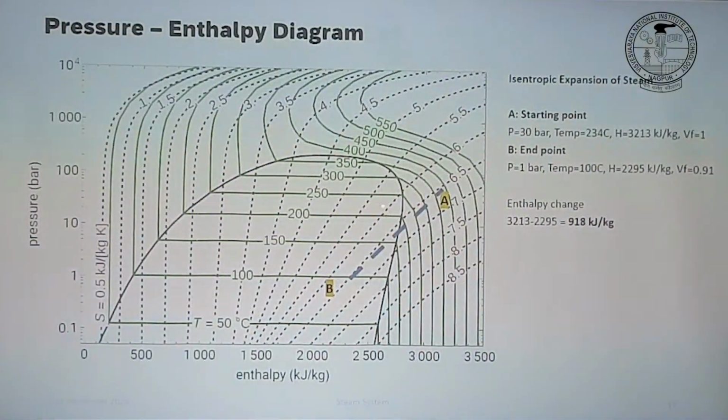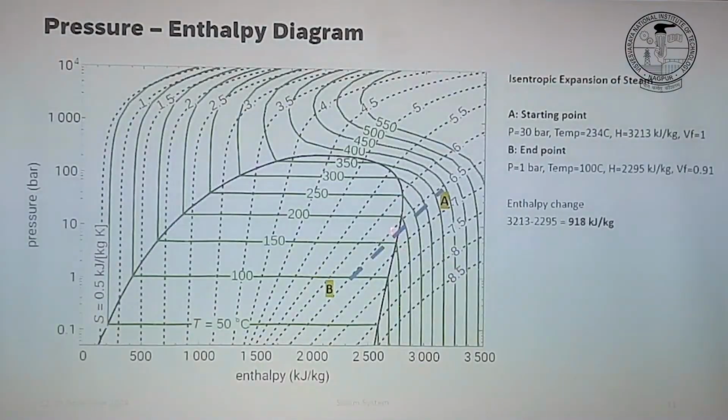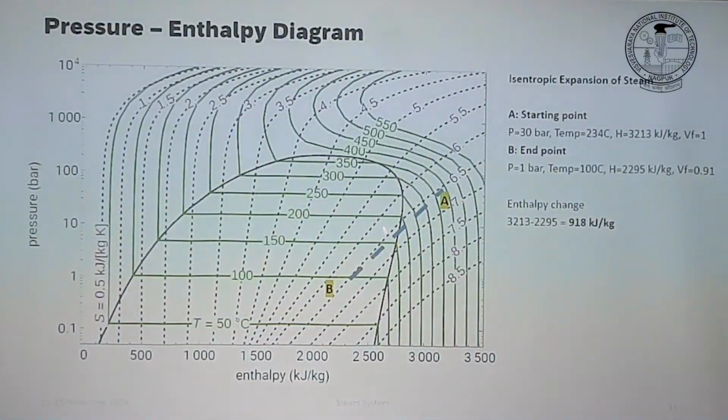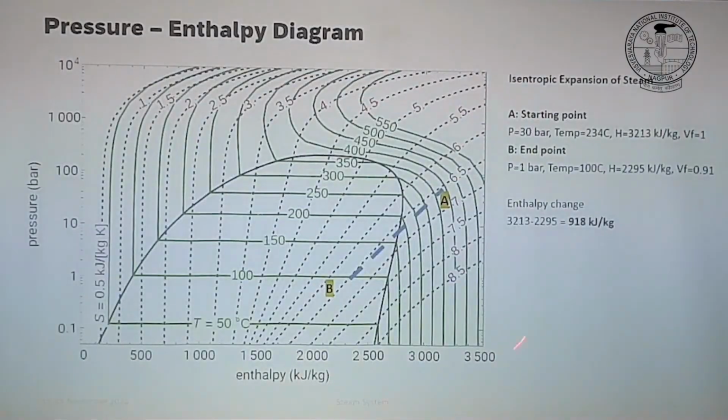What else can we do? We can superheat the steam, right? So we are not at the saturation curve, but now we move from the saturation curve to the superheated region, thereby increasing the enthalpy of point A. Right? And with this, you now have much more energy extraction.